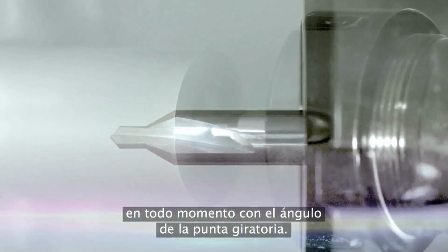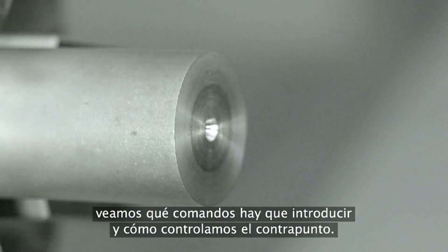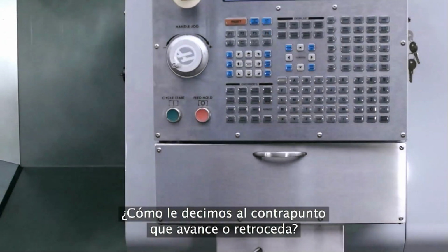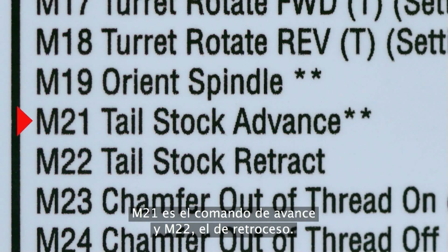Always use a 60-degree center drill so the angle of the drilled hole will perfectly match the angle of the live center. Now that our part has a center hole, let's move on to how we command our tailstock and control where it moves. So how would you tell the tailstock to move forward and retract?